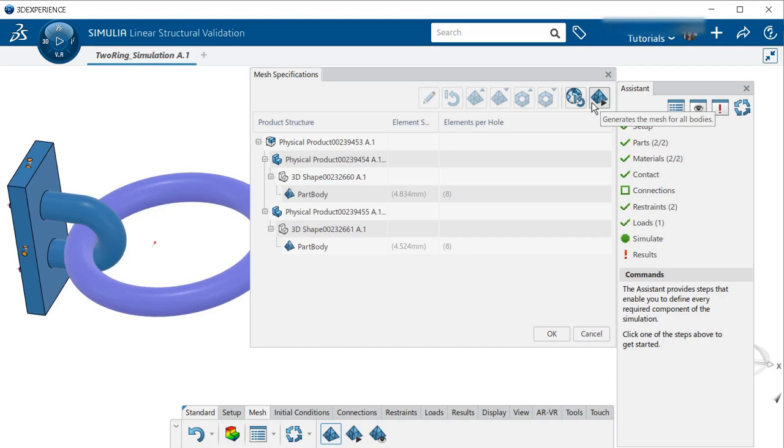Mesh control is an important factor in determining the accuracy of the results. A coarse mesh implies reduced computation time and resources. However, the results might not be sufficiently accurate. A fine mesh, on the other hand, implies longer computation time and resources, but improved accuracy of the results. Mesh refinement is especially essential in regions of high stress concentrations, such as near regions of contact, or sharp features